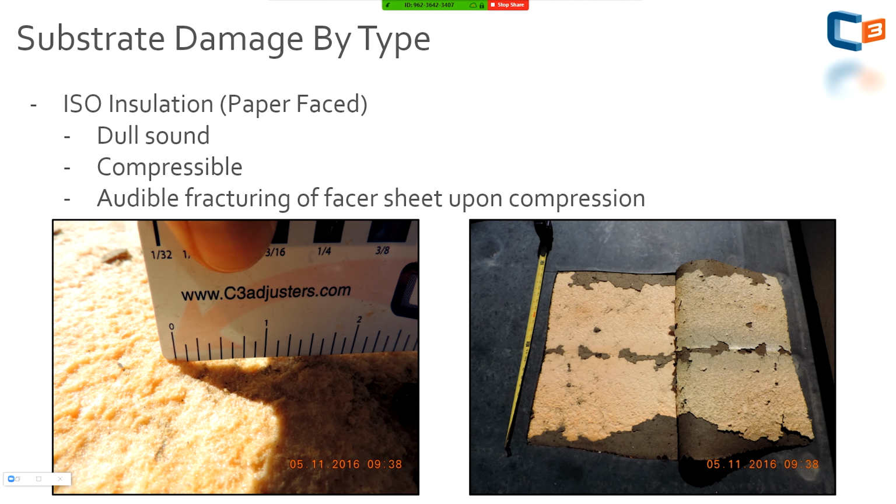So this is an example. You recall the EPDM membrane where I drew out a 2x2 test area. This is what happens when I pull that back. And again, this could be EPDM, PVC, TPO, doesn't matter. But I'm feeling those depressions before I make the cut in a single ply roof system. And I pull that back, and I'm documenting those depressions.